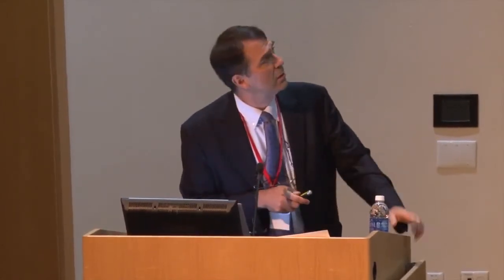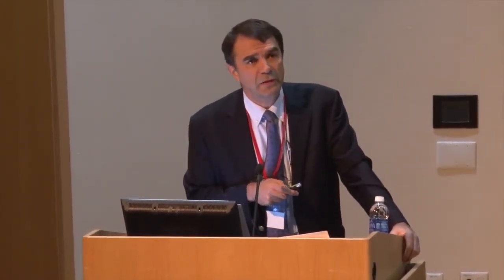I was wondering what the effect is of the mechanical properties of the top plate. In other words, have you experimented with anything other than silicon? Well, of course it's in the picture. If you use a stiffer material, then you can make it thinner for the same performance. But these factors all affect each other. Some people are using diamond films, but when you have a diamond film, it's very stiff, so then you have to make it thinner.